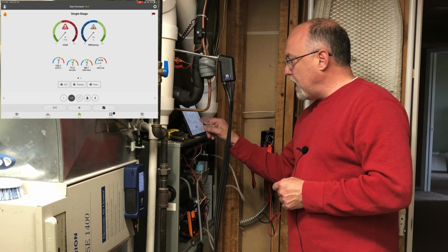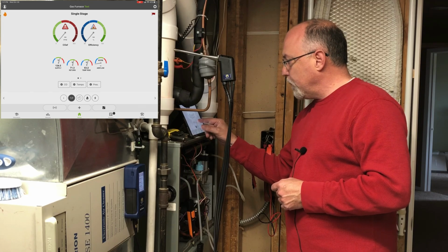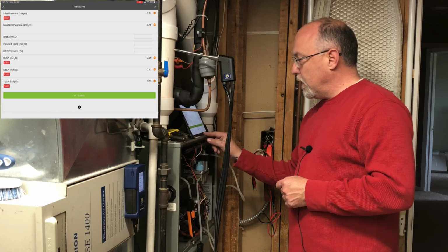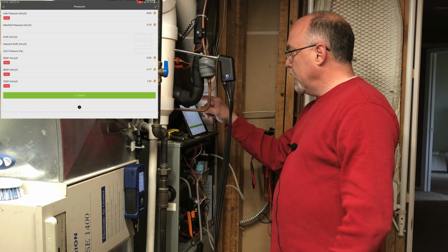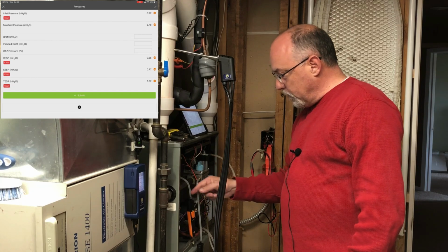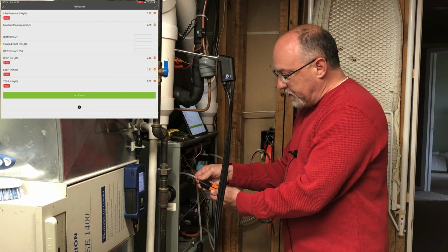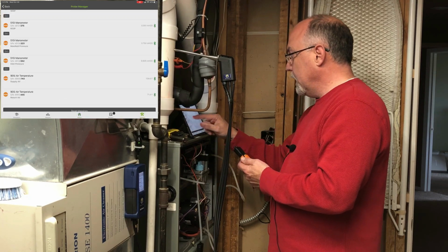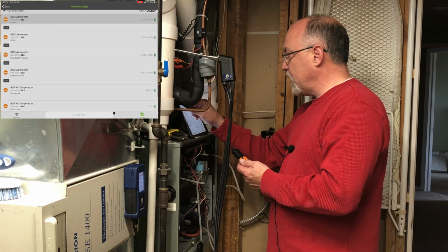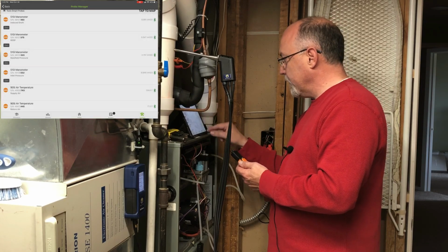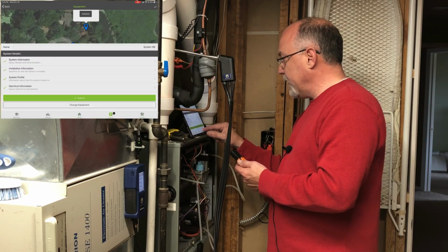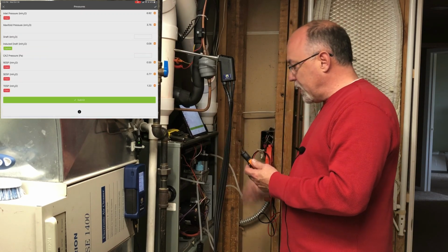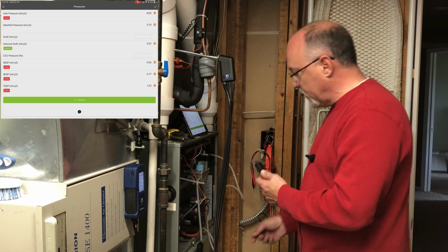And I can move these around too. So let me show you this. Let me go back into the pressures again here for just a second. So you can see my induced draft pressure right now is a field input box on there. So what I'm going to do is, now that I have my static pressure done, I'm just going to remove my supply static manometer, and go to toolbox, and my supply static here, I'm just going to remap it to induced draft pressure. Go back to home or project here. I'll go back to home, go back to pressures, and now you can see my induced draft pressure is 0.08, just the manometer, just a little drift on there.